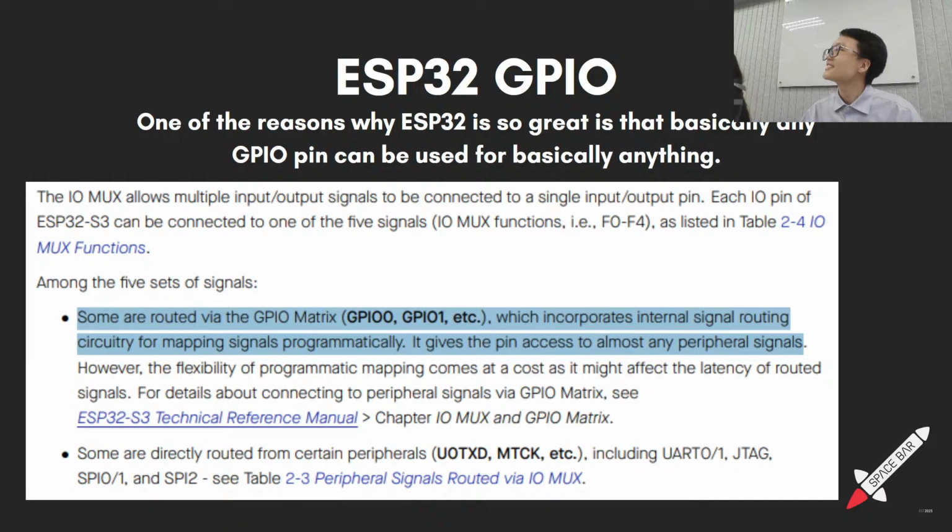Okay, I apply any voltage to the pin. Let's say my pin accepts 0 to 3.3 volts, and I apply, I don't know, 2.2 volts to it. The GPIO pin, through magical means, will tell me, yes, this is 66% voltage.